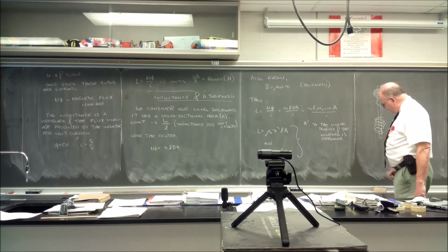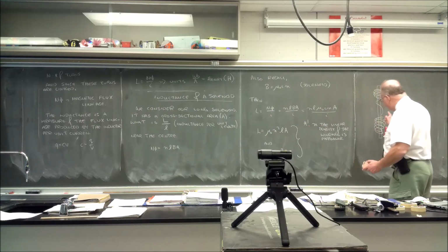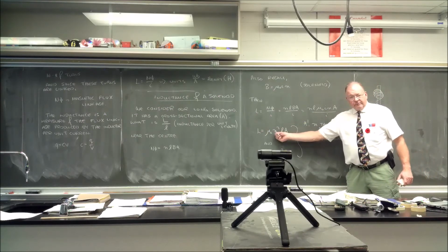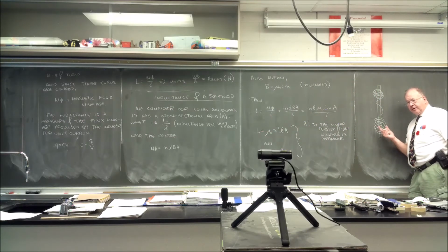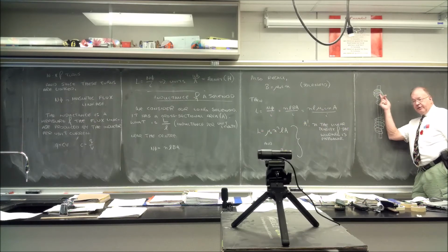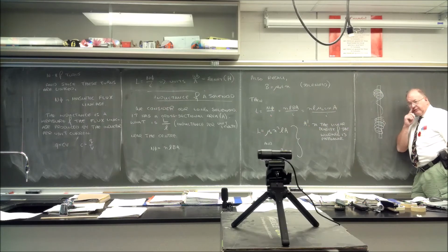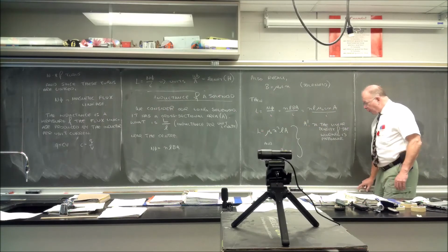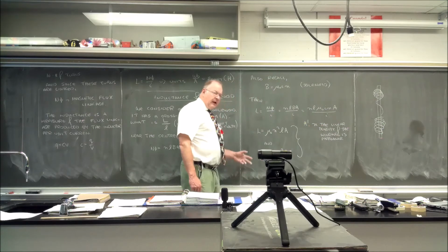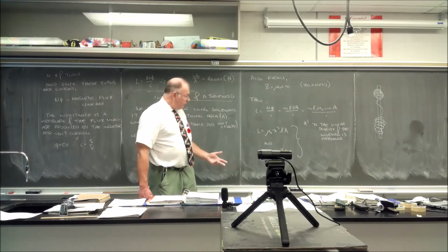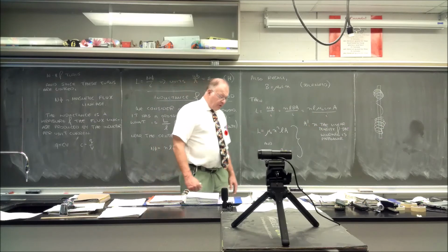So that's why you can do this, because it's a function of n squared. So here we have, let's say 50 turns per unit distance, whatever that would be. That would give us 2,500. Here we have 1, so that's 1. Then we have maybe 30 here, that's 900. So the inductance here and here is quite significant, and here it's irrelevant, as an example. Now, of course, it'll depend on what you're doing and how much of the inductor you're actually dealing with, as to whether you were to use this or this. And that depends, of course, on the application.